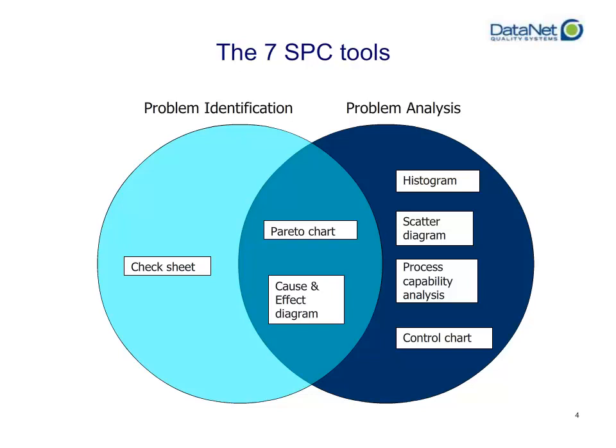We have scatter diagrams, which we can use to correlate different variables, whether or not there's a relationship, and if so, what kind, and that allows us to analyze the relationship. We have process capability analysis, which gives us a grade on how our process has either improved or degraded now versus previously, and how it actually is right now, how our process is actually behaving. And then we have also control charts, where we are able to, in real time, view what the state of our process currently is.